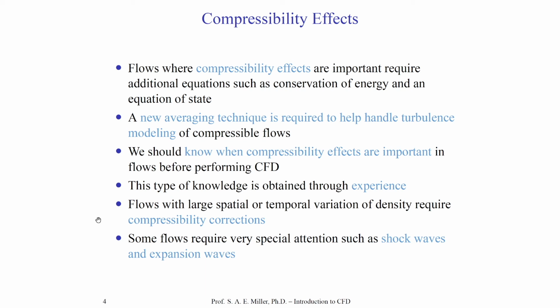They may not necessarily need modification of the equations and turbulence models which we're showing, but they would require specialized numerical methods. We already discussed shock capturing in this class, and those same shock capturing methods, like in the visualization section, can also be applied to the solver itself, not just visualization, to capture the shocks. Remember, the shocks are very thin, and of course the number of grid points to resolve them would be extremely large.